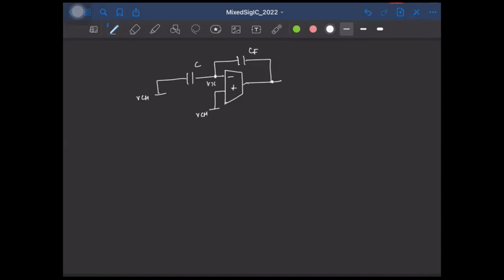And if I call this voltage Vx, till the point the current required from the OTA, that is Gm times Vcm minus Vx, till this becomes less than the bias current of the op-amp, we will have slewing, right? So wherein we have a constant current charging the capacitors like this. Okay. And the moment Vx falls to a value such that Gm times Vcm minus Vx is equal to IB, then the slewing will stop, right?